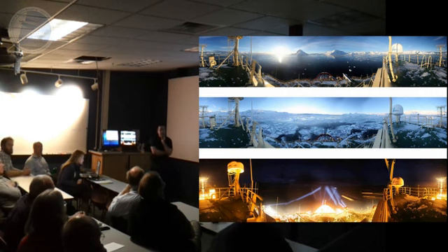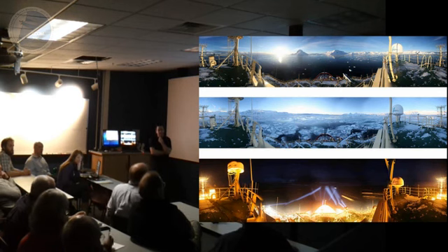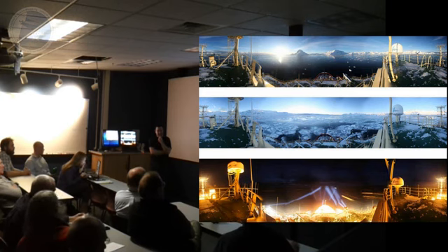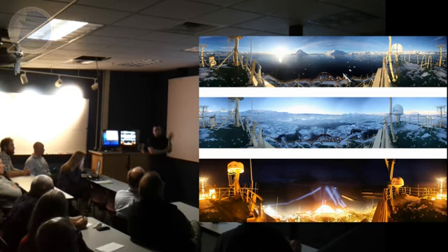The comment is that the problem you mentioned, of determining the positional offsets and angular misalignments between the IMU frame and the camera frame, in the photogrammetry world is called the boresight calibration, kind of similar to a patch test on a ship. There are some automated algorithms for that. I don't know if you've looked into it, but you don't necessarily have to reinvent the wheel. I can point you in the right direction if you're interested.